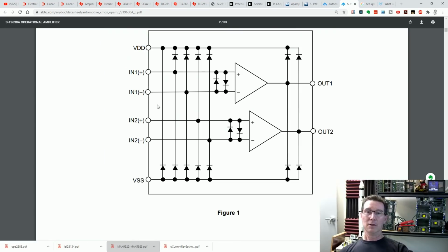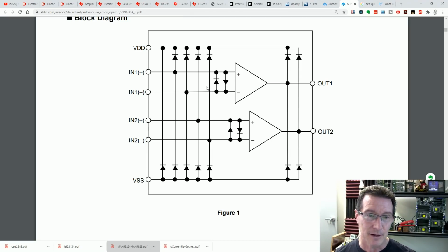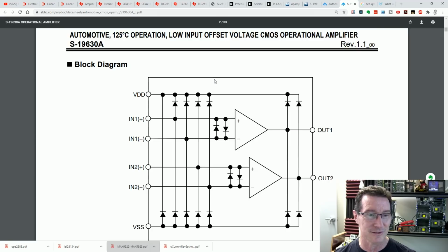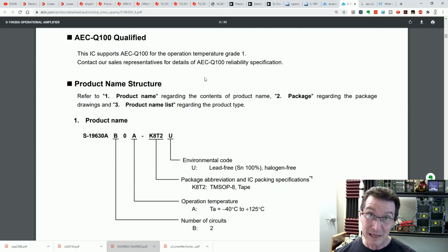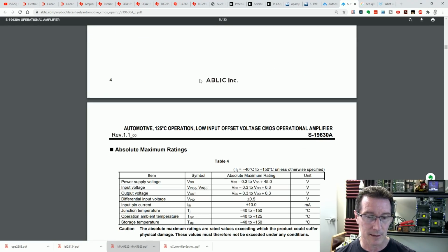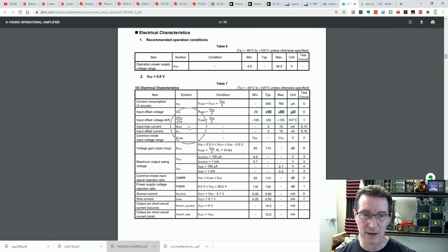Oh, gee, what's the collective term for diodes? They've really gone to town. There you go. They've got the anti-reverse parallel ones. They're anti-mux. You remember that? So we've got protection everywhere. We've got one diode right across VDD and VSS, and on the inputs and outputs, and they're probably beefy too. Being automotive, they really want to clamp that protection. So anyway, that's not going to set the world on fire, but hey, automotive jobby.